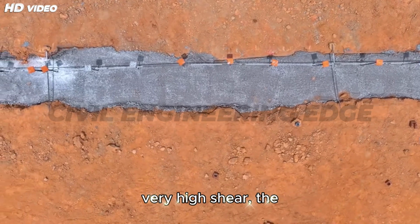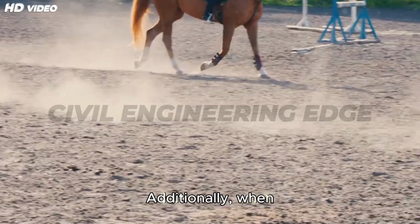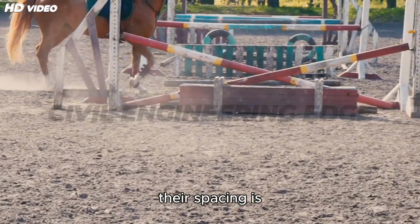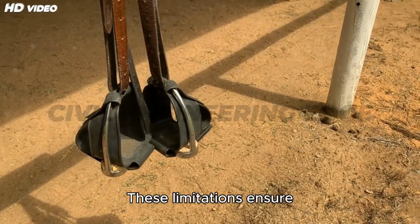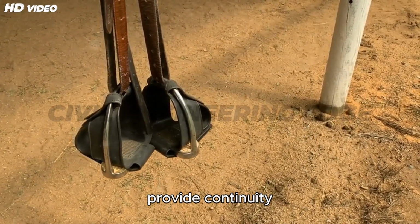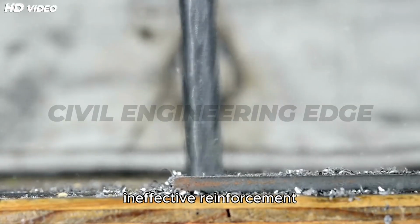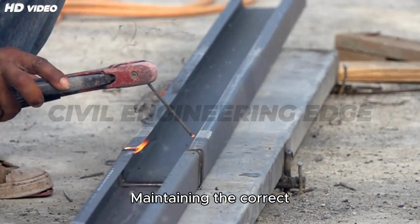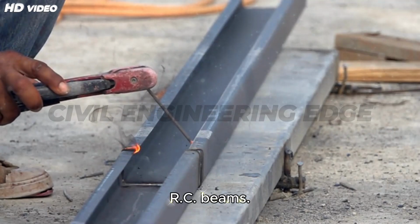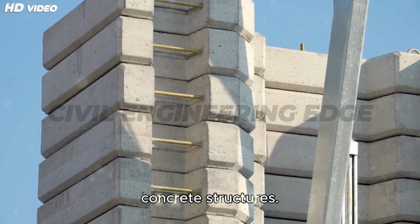In members subjected to very high shear, the spacing may be further reduced to improve crack control. Additionally, when inclined stirrups or bent-up bars are used, their spacing is adjusted as per geometry. These limitations ensure that stirrups can effectively intercept diagonal cracks and provide continuity across cracked sections. Exceeding the prescribed spacing leads to ineffective reinforcement and wide shear cracks. Maintaining the correct stirrup spacing enhances ductility, toughness, and post-cracking behavior of RC beams. It's a key factor in both safety and long-term performance of concrete structures.